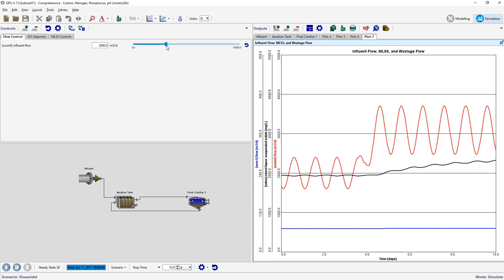Once the proportional gain is stable, adjust the integral time to increase the controller performance, and if there's too much overshoot, try increasing the derivative time. The integral term is responsible for driving the steady state difference between the set point and process value to 0. The derivative term controls the rate of change of the errors and thus controls the amount of overshoot. Run a few more simulations adjusting these PID controller settings. Process control can be a complicated subject, and more information regarding PID control is available in the GPSX Technical Manual.